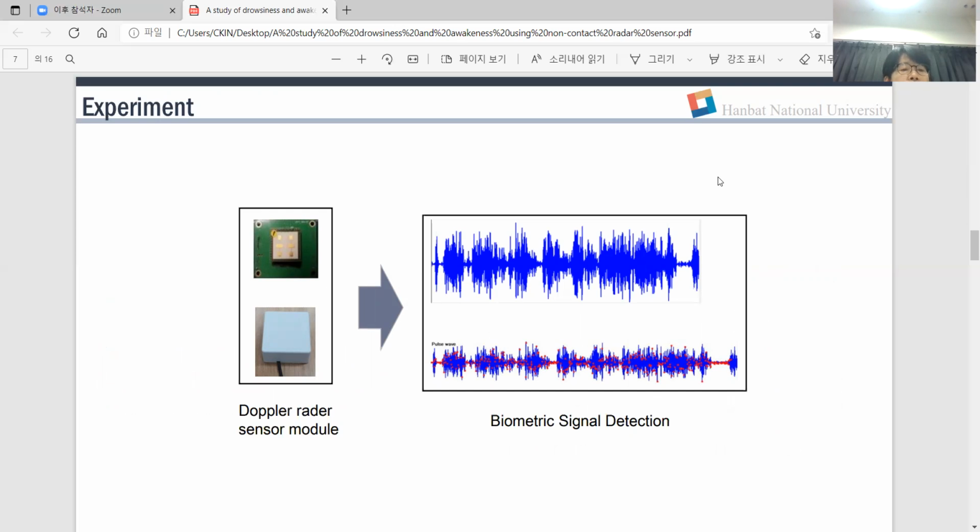We propose a gigahertz Doppler radar sensor system that can measure remote biological signals with only a simple hardware configuration. The proposed radar sensor system includes a commercial chipset and flat-type passive device, considering characteristics of radar wave attenuation in the body according to the operating frequency characteristics. RF front-end modules were developed using an antenna, etc., and high sensitivity signal processing algorithms were applied to obtain biosignal information in the time domain. The biosignal acquired through the radar is displayed by calculating respiration and heart rate through the signal processing.